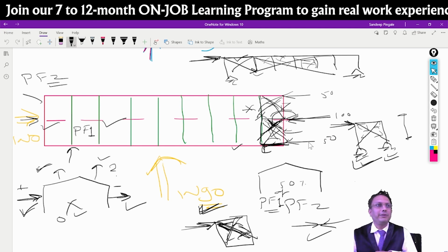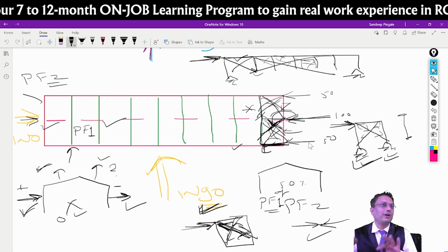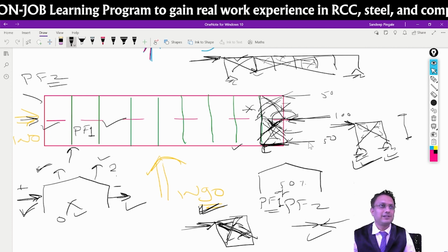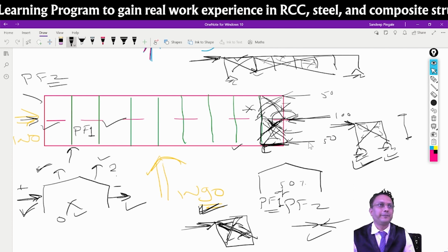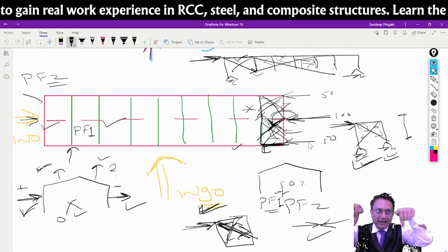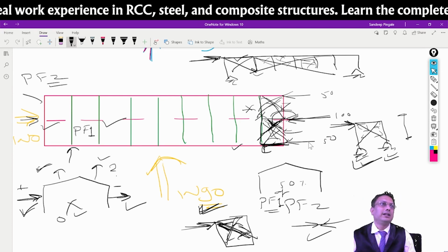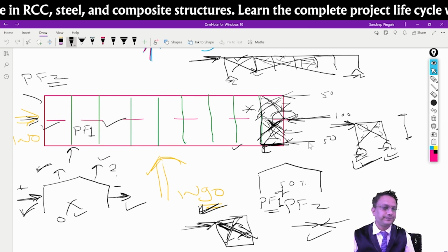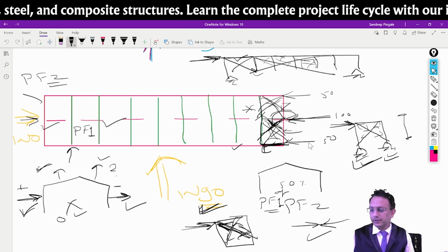And that kilonewton per meter, you will apply in the ETABS model or STAAD model, SAP model, whatever software you use. So what does it mean for an inclined member? For an inclined member, it is always perpendicular to the local axis, not the gravity direction. Yes. Understood?